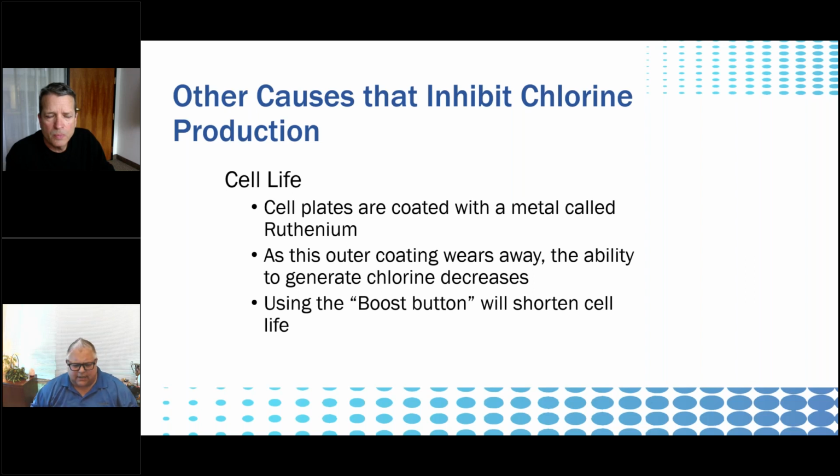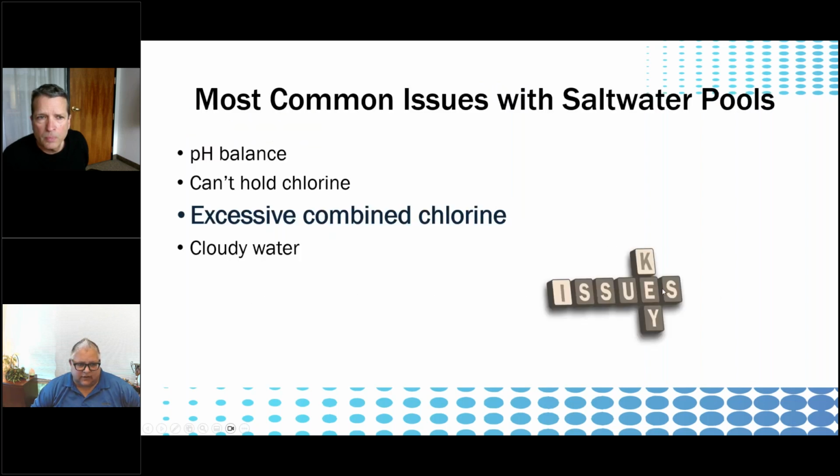So people ask me, you know, can I use the boost button to troubleshoot cloudy water? Can I use the boost button to troubleshoot algae? So if I owned a salt pool, I'd never use the boost button. And that's just my opinion because it makes it really hard on the cell and you're shortening the life of the cell every time you do it. Again, it's okay to shock a saltwater pool. It's okay to add secondary chlorine in order to help you troubleshoot. Relying on the boost button, it's a bit of a challenge to figure out exactly how much chlorine you're actually going to get out of it, and also is it enough to overcome the problem that you've got.